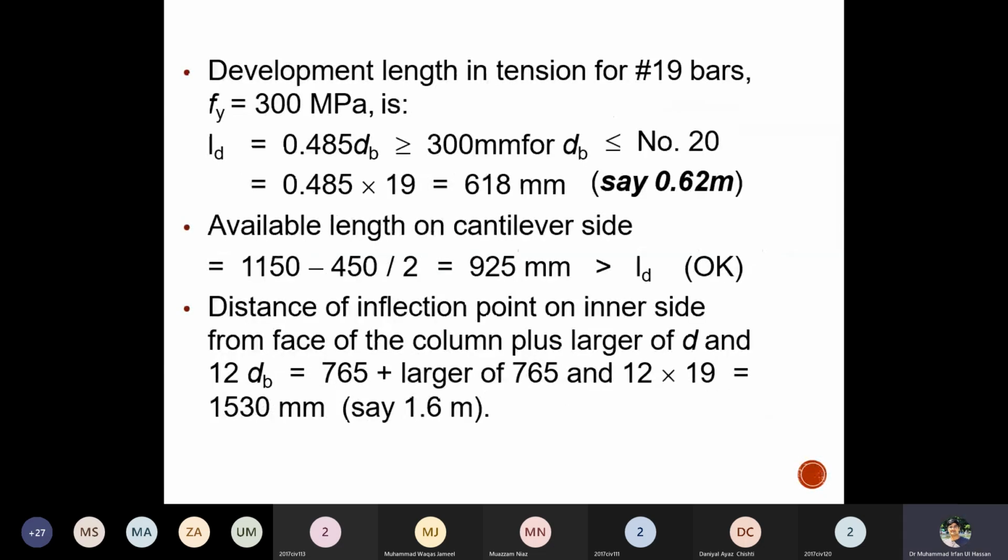Then the development length expression will be similar. You know that the bars cannot be curtailed before the Ld plus d. So as per the criteria, the dowel bars are also needed, which are to be spliced with the column and extended into the footing. So you must see some detailing of the combined footing, and then from the detailing guideline, this Ld can be obtained.